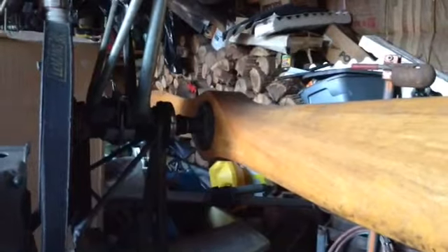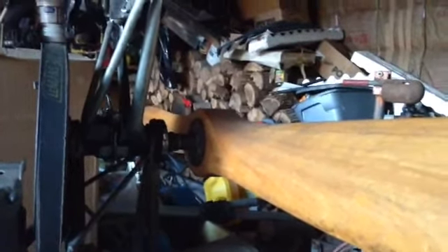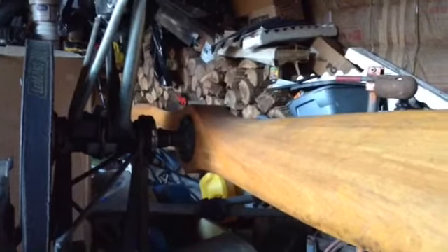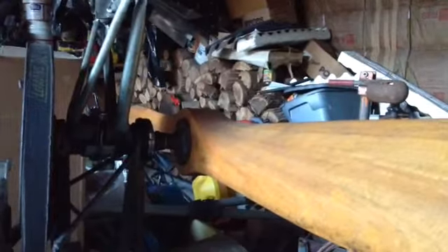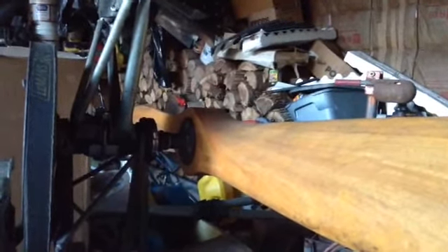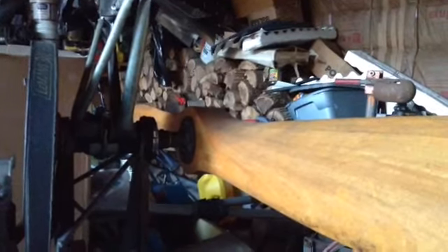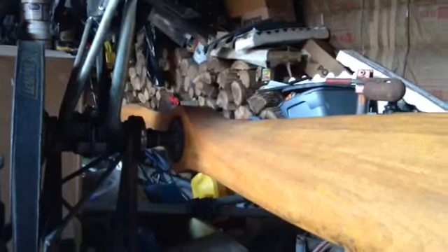So we saw with our bicycle wheel hanging by an off-center rope tied to the axle that torque applied to a rotating body causes precession. Conversely, forcing a rotating body out of its plane of rotation and into a different plane of rotation, not parallel to the original plane, causes a bending moment on the shaft that is used to change the rotating body's plane. This is a 3/4 inch shaft hooking to the propeller.